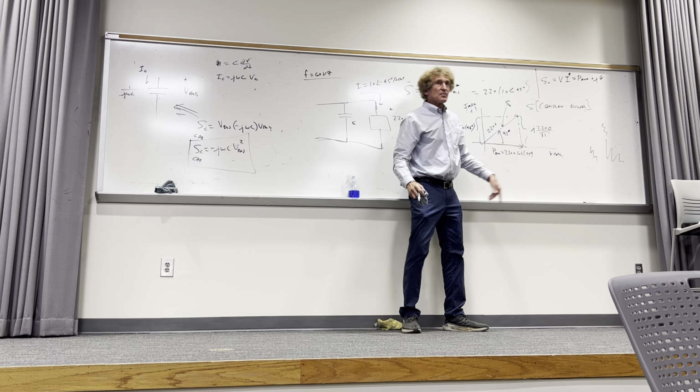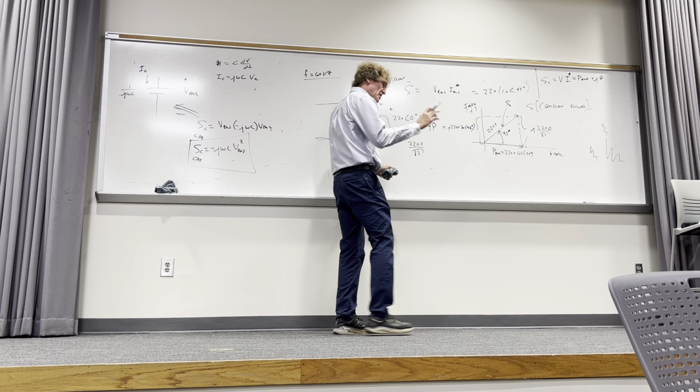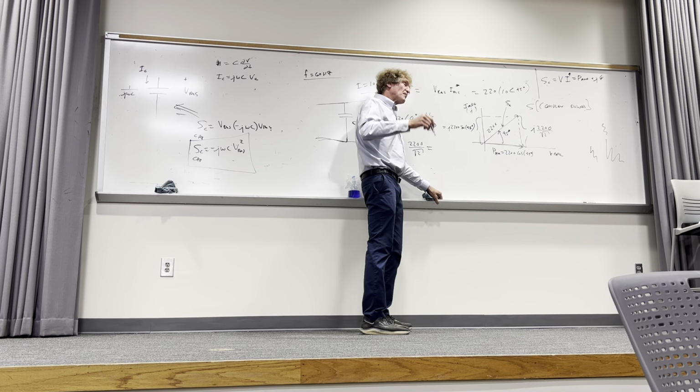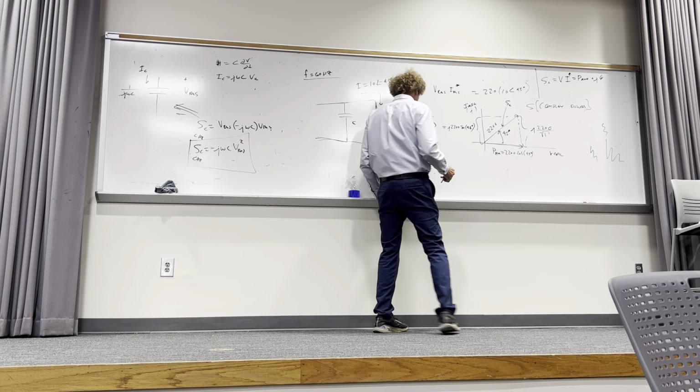That's the magnitude of the positive j term. And I set it equal because I want a power factor of 1, which means an angle of 0. There's no reactive power, no plus or minus jQ at all at the end of the day.